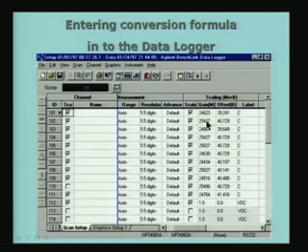So, for each channel I can have a different formula, or it may be the same if they all have the same constants or coefficients given here. So, for each channel I can have a different formula, and then I can convert the input to the channel in terms of voltage to degree Celsius, and that can be done here.